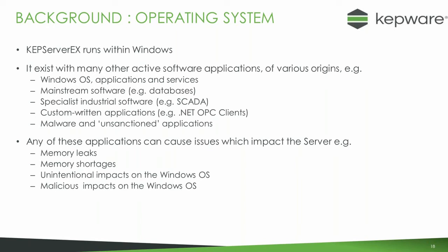So these software applications can impact what's happening on the Windows operating system, and therefore that will impact what KEPServer is seeing. You can have memory leaks, you can have memory shortages, you can have all sorts of things happening within the OS, malicious or unintended, which will then cause KEPServer to not behave as it should.